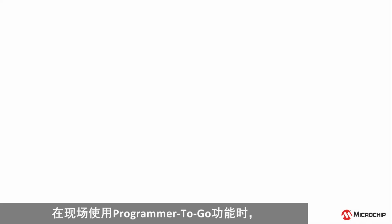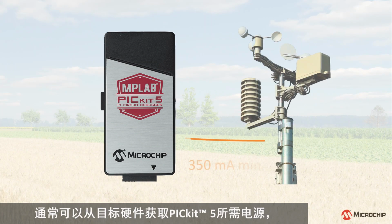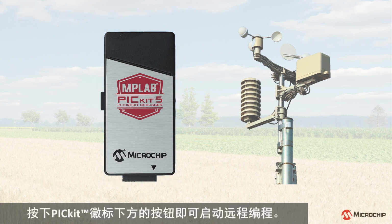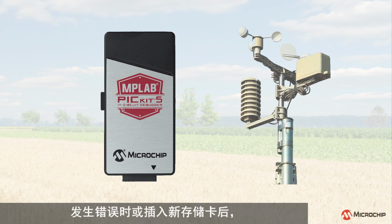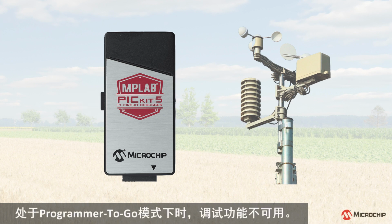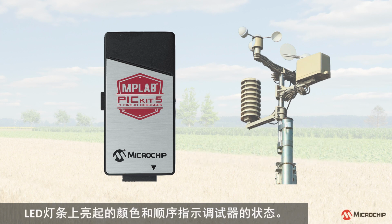When using Programmer-to-Go in the field, power for the PICkit 5 can often be obtained from the target hardware, so typically only a connection from the tool to the target is required. Remote programming is initiated by pressing the button under the PICkit logo. Press and hold this same button to reset the PICkit 5 in case of error or after inserting a new memory card. When in Programmer-to-Go mode, no debugging facilities are available. Colours and sequences illuminated on the strip LED indicate the debugger's status.